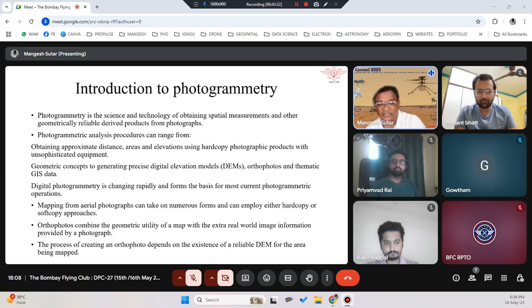Okay, so whenever a project is released by any organization, they will ask you how much overlap you need between subsequent photos. Normally they will tell you 60%, 70%, or 80%. With that overlap, they would also define how much zoom, or resolution, should be possible, like 5 centimeter, 3 centimeter, 2 centimeter. All these parameters would be defined when they are asking you to capture the data.